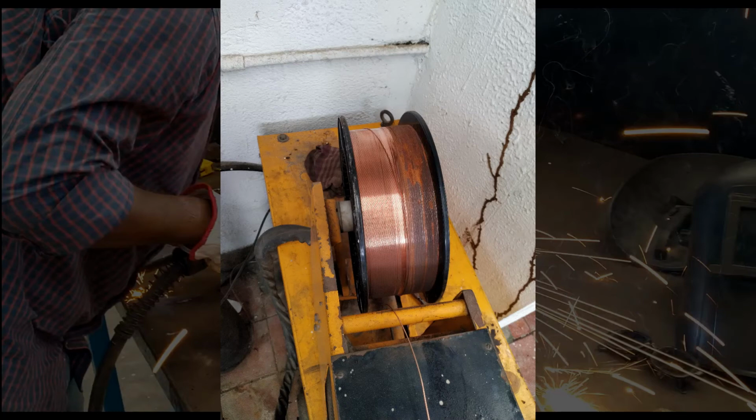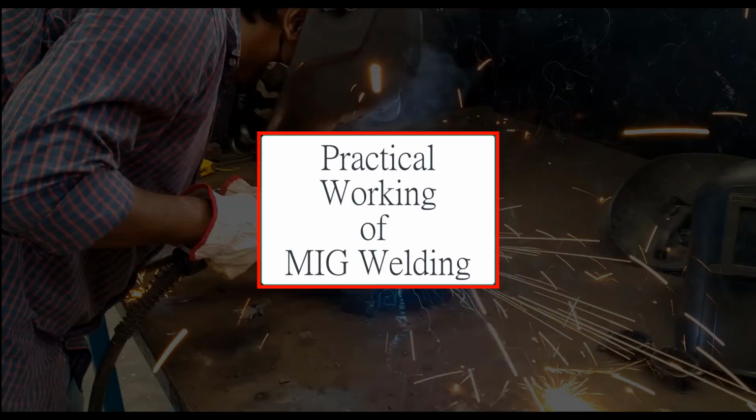Here the electrode is used for generating the arc, and this is our metal rod that is continuously consumed during the process. It means that just by melting, your wire is continuously required in this process. So we are using this type of wire that is continuously melting, and with the help of the motor we can continuously feed the extra wire from the supply of our continuous wire roller, right? We are using the roller on which wire is wound, and just by the motor we can continuously feed this wire into our welding process.